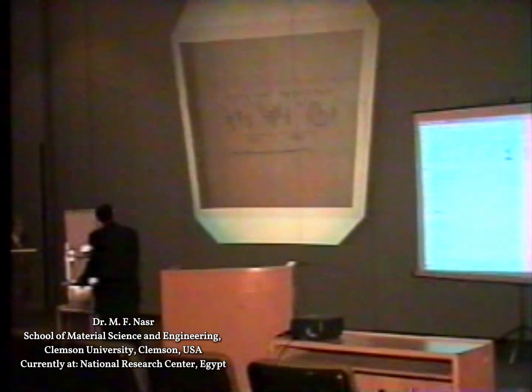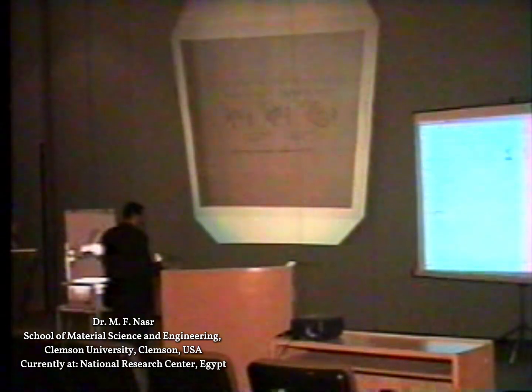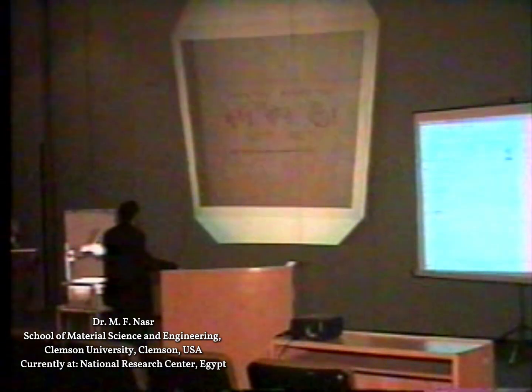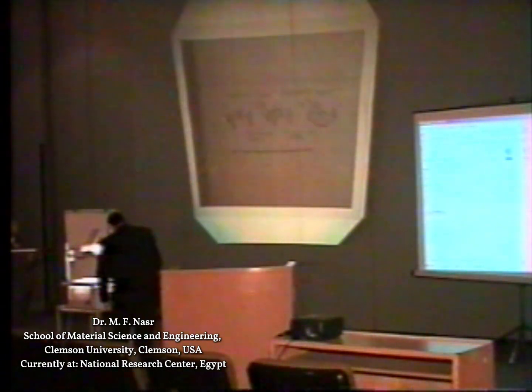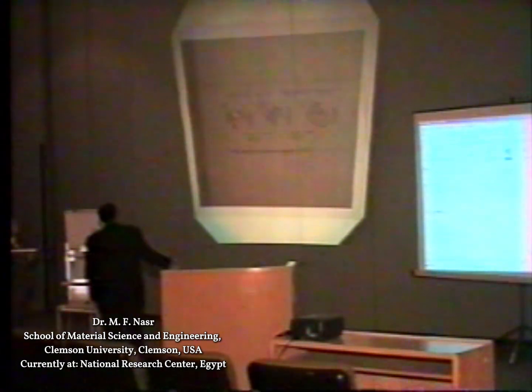And here is the mechanism of conduction. Here we can represent the small crystallites in the ACF by these small circles. And now the electron can hop on the boundary and into another crystallite, because, like I said, this is considered to be a pore due to the activation. With increasing the temperature of carbonization and graphitization, the graphitic layers start to grow a little bit and it becomes easier for the electrons to move between the ACF crystallites.